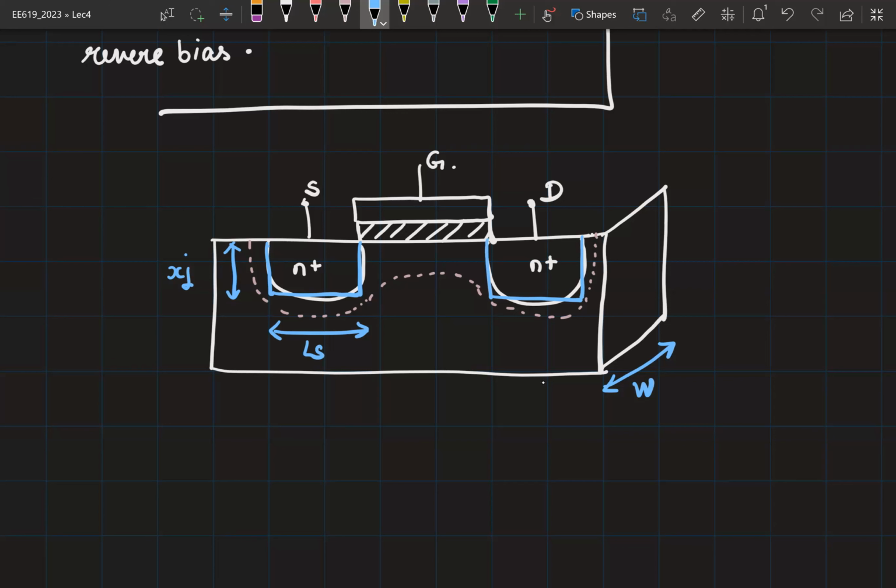Is this okay? Right. So now we have to find out all the areas associated with this diffusion region that can result in a capacitance. What comment can you make about the bottom plate? So you have to assume that the rest of the region is P. So there is the bottom plate that is in contact with the P surface. You can expect to see junction capacitance.